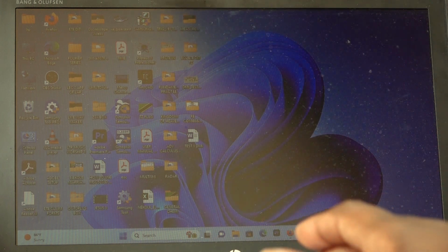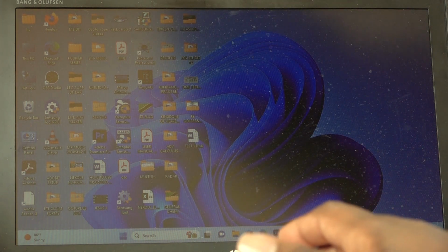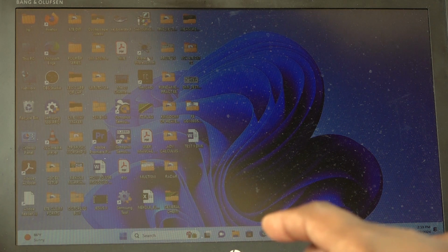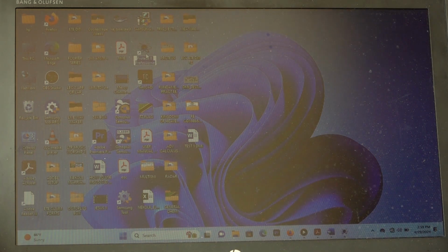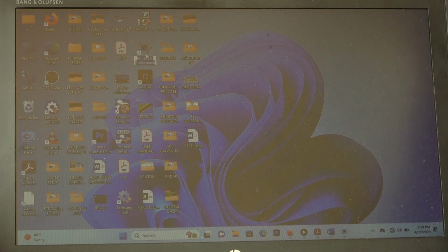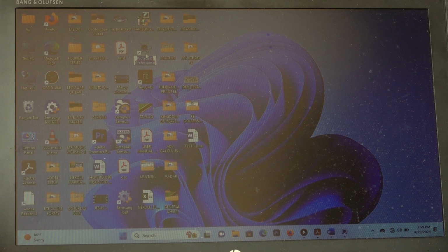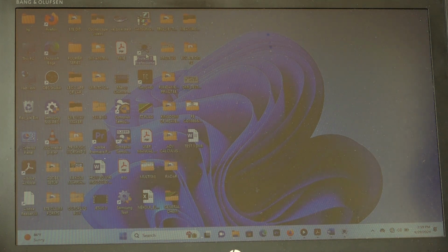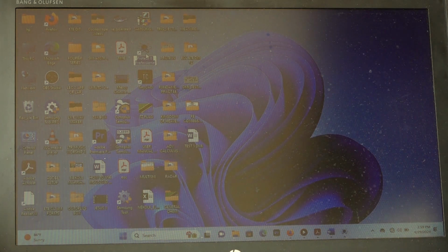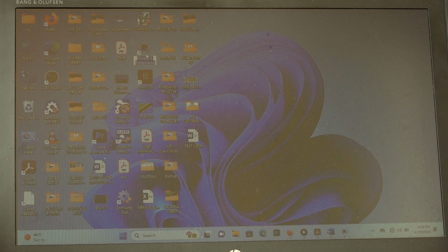So I have the simulation software called Proteus. This is the setup, or the desktop shortcut. I have told you, and I'd like to repeat, students, I ask for your attention: whenever you are opening the Proteus setup, whether on the desktop or in documents or wherever it is, make sure that you run it as administrator.